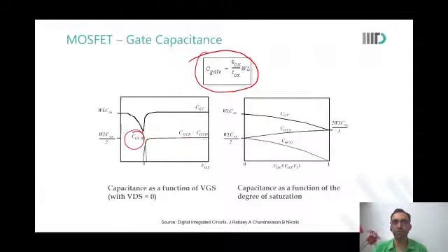Vaishnav, you have a question? Rajneesh? Sir, in this first graph, the gate to source and gate to drain capacitances both become half after VGS is greater than VT. Sir, is this because of the uniform channel formation? Yes, because VDS is kept at 0.